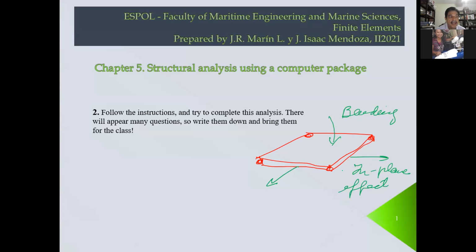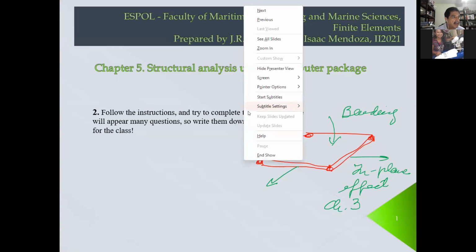Okay, this is what we studied in chapter 3. The bending of the plate we did not analyze here in this course, but you remember the concepts of bending of plates from the previous semester. So in this case, we're going to use this type of element in order to discretize the structure. And you can see, of course, immediately that the number of joints is going to be much larger. And of course, that means that the number of calculations that the computer has to perform is higher.